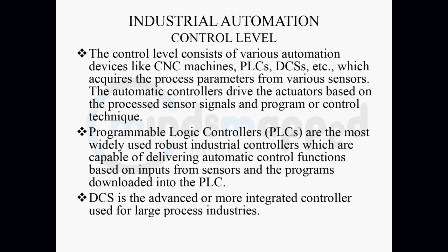So what they want to try to tell us is that your PLCs are sensing the data, receiving inputs from your field devices, and based on those sensed signals and the logic that they have in their memory, they will evaluate and take a decision and transfer their decision as an output command to your output element in the field, and that is how the control is being done.